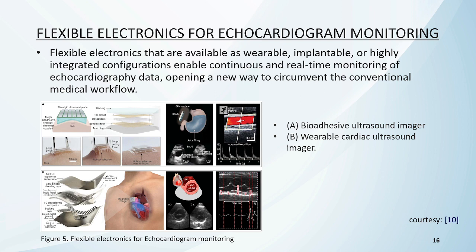Then the wearable cardiac ultrasound imager. The first figure of section B shows the flexible probe, which consists of piezoelectric transducer arrays, liquid metal composite electrodes, and a trivalent copolymer electrode. Photographs from several views are shown in the second figure of section B.